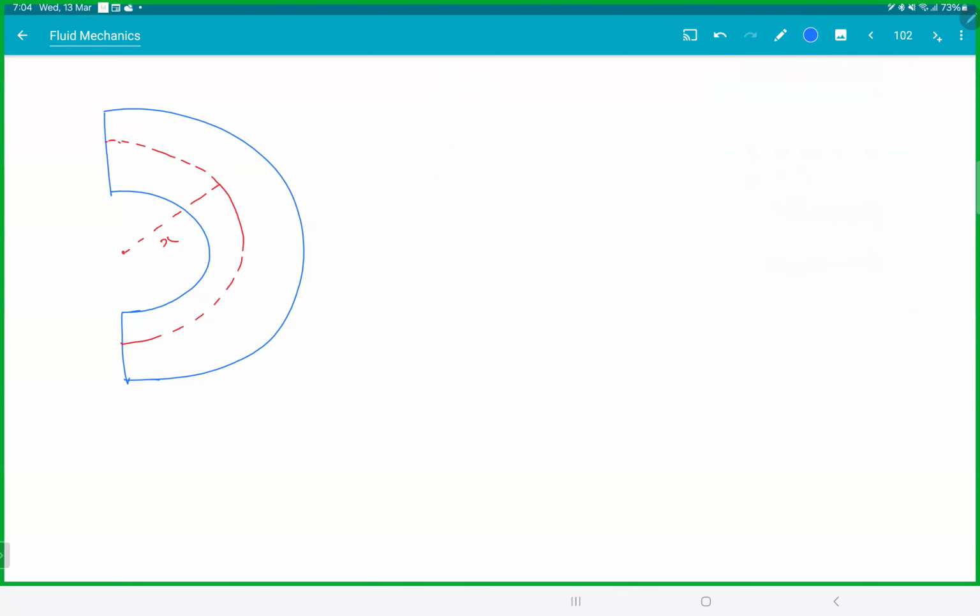Okay, so the thickness is how much? T, no? So the area will be how much? Circumference, which is pi into x into t. Agreed? Able to visualize, you'll get a semicircular wall, whose circumference is pi x and the thickness, the height, is t.